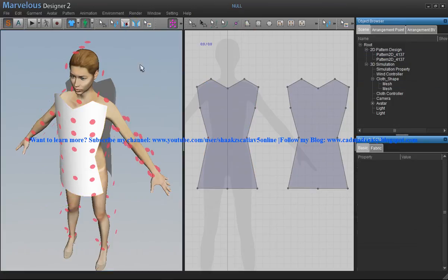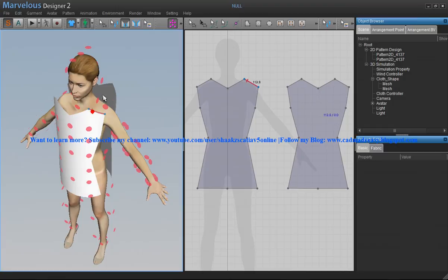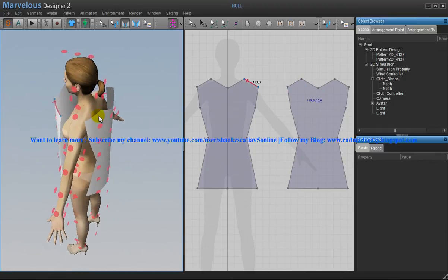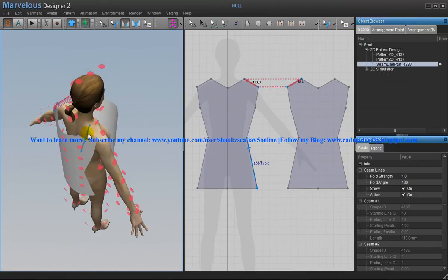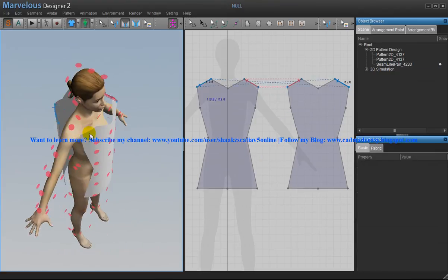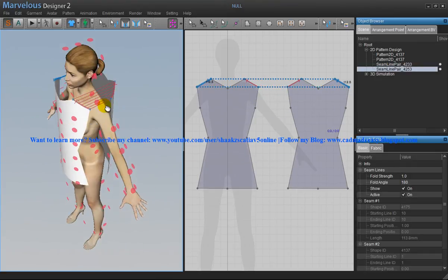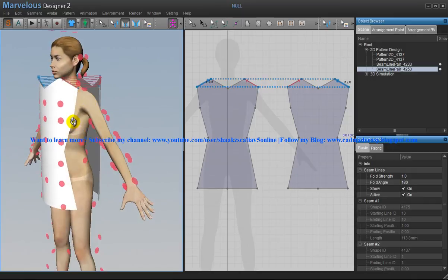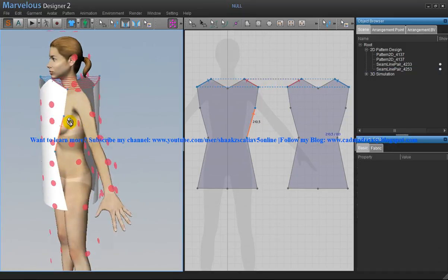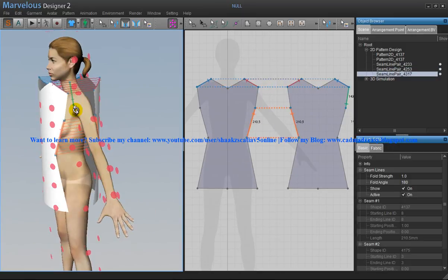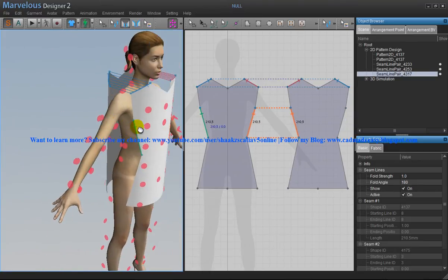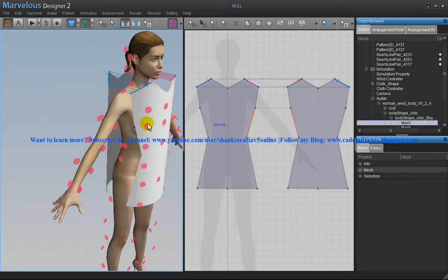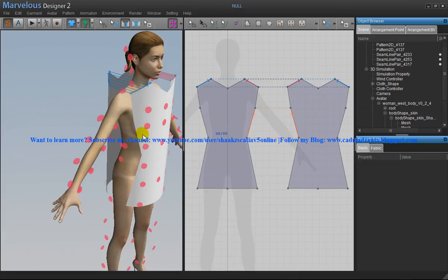Now use the segment sewing button and sew this and this and this one and this one. Don't sew it from the same view, because you're gonna get confused. Sew this portion and this portion, because this has to be open, because that's where the hand comes. And again, if you get it wrong, then press escape, change the tool, come back again,